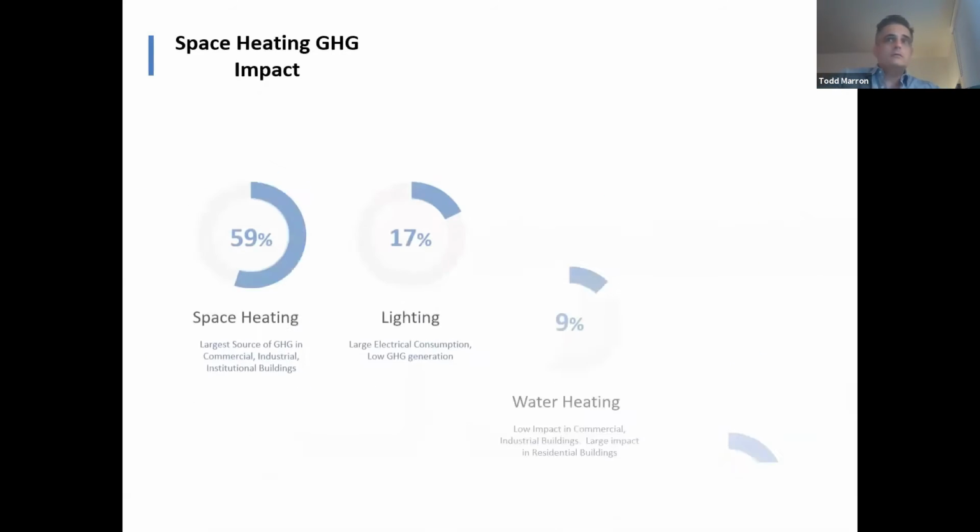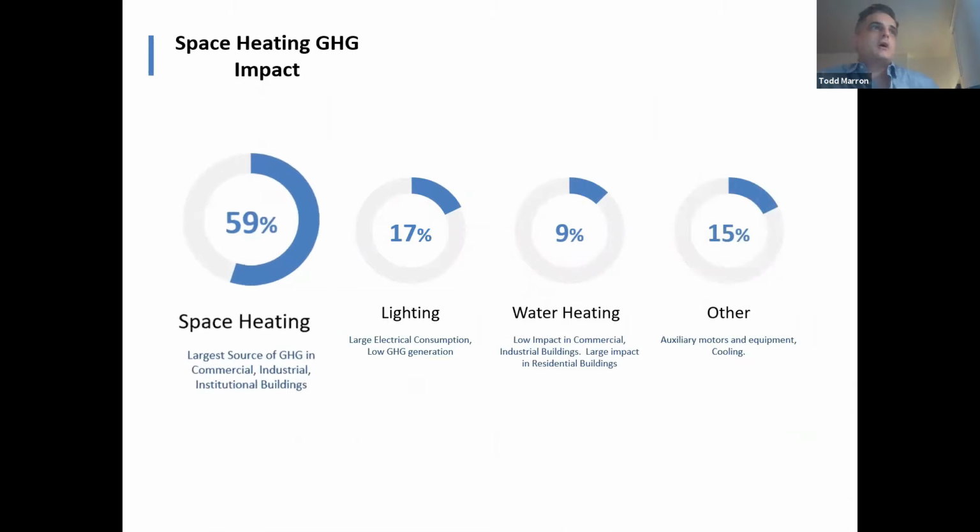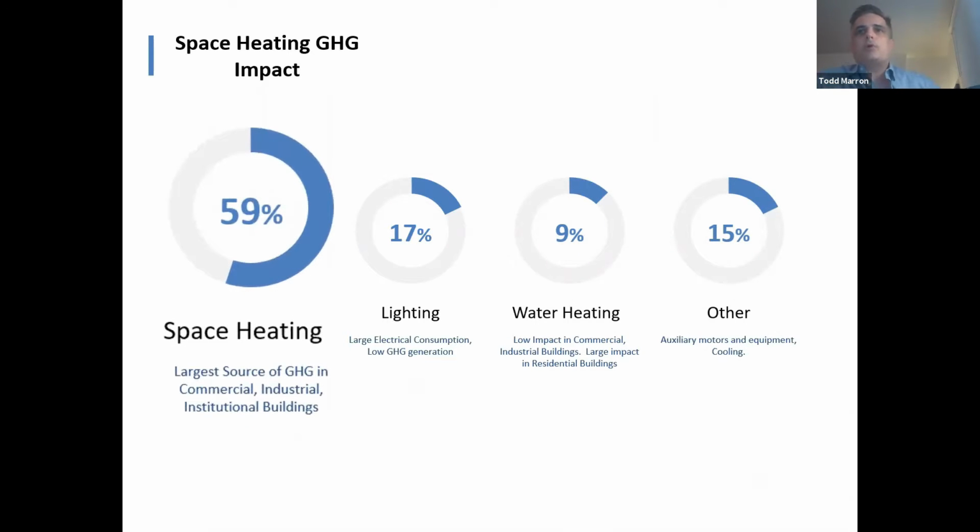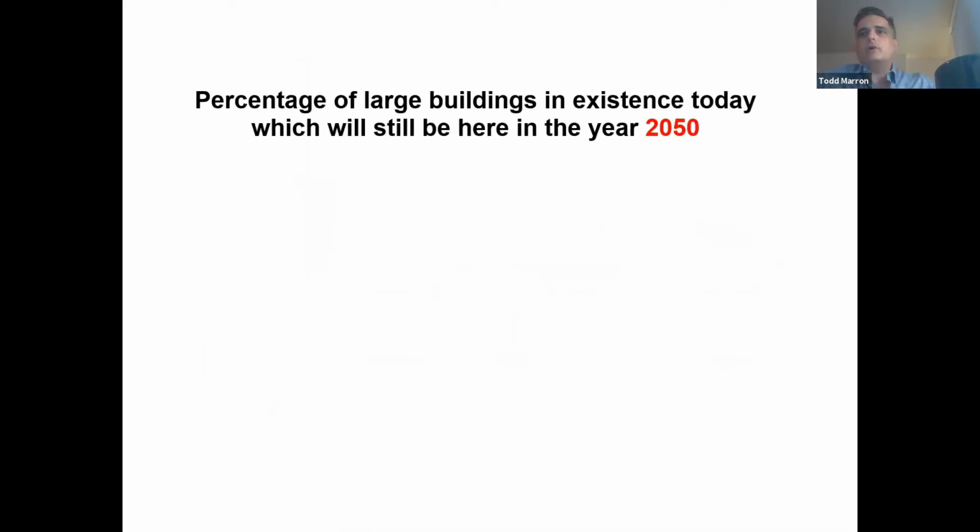And the reason why the technology has the popularity is we've got a pretty big problem that we aim to solve. So keeping in mind that SolarWall is designed to preheat ventilation air for buildings, if you look at the GHG impact on your building, that's a big energy hog. That's space heating, and specifically the ventilation space heating. So if you think of, say, a factory with some welding or something going on, you might have 3 air changes an hour, maybe even more. So if you've got 3 air changes an hour, you've got to reheat that entire building every 20 minutes. So if we're able to carve out 20, 22, 25% of that ventilation heating load, it's a very big percentage of the overall impact on that building.